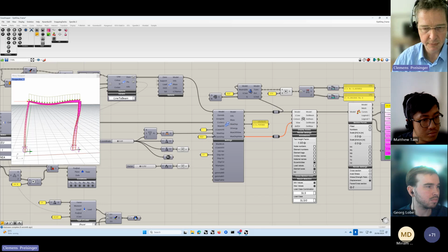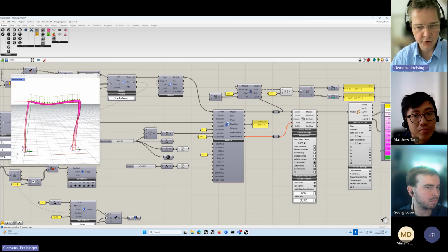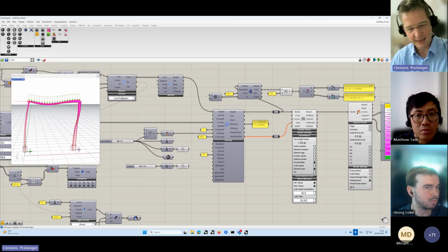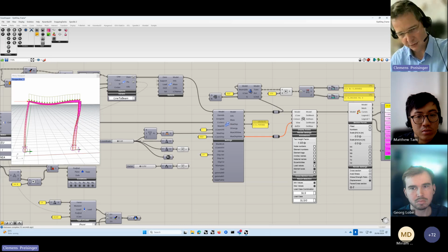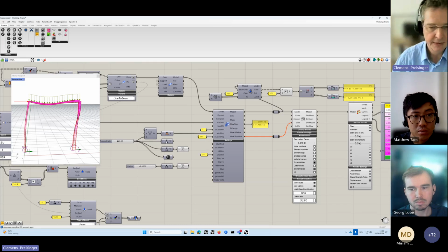So for example, in this case, it's the same as supplying here a limit in x direction. But for three-dimensional cases where there's a movement also in y direction, that makes sense. And so I can now also limit the displacements via this plane here.